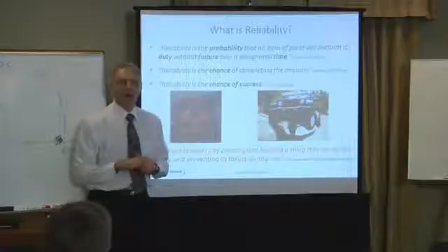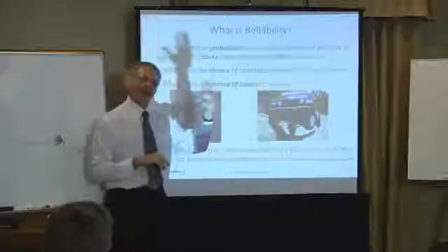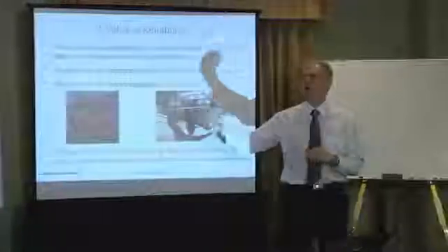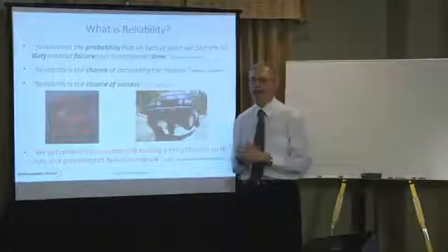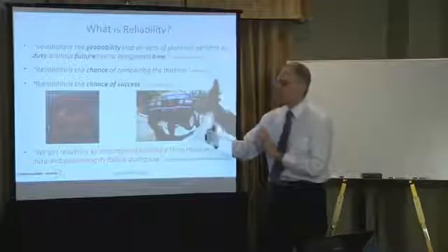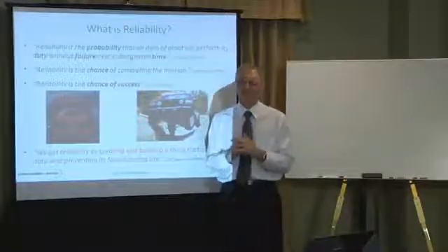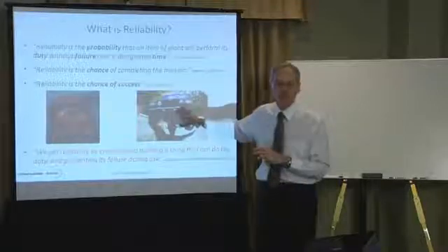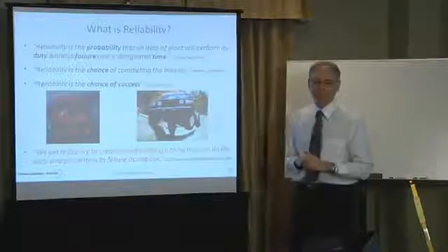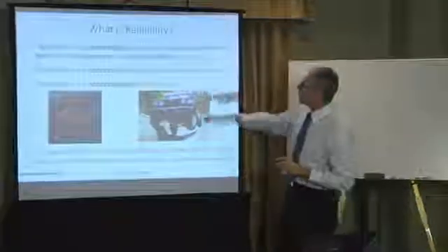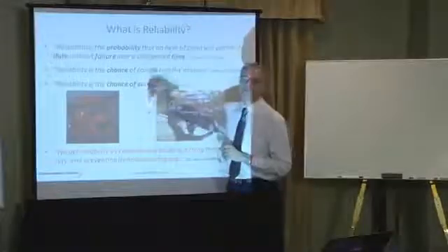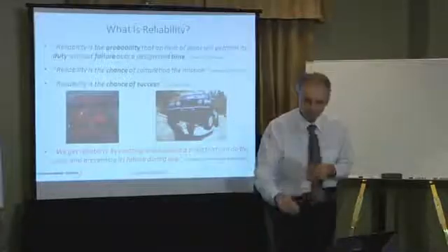So that's why the life cycle concept is so vital. If I get it wrong at the very beginning, then no matter what happens in the coming years, I cannot do any better than what the design allows me to do. So that early day choice, that first day choice, everything else hangs off that. And if the wrong machine is chosen for that job, it will always be a problem. So if the chance of success is low from the beginning, then I will always have poor reliability.